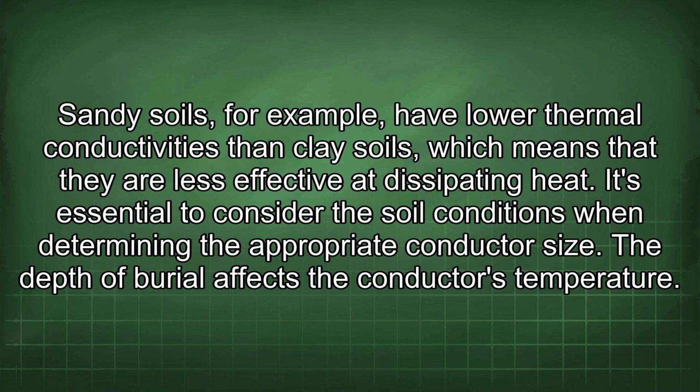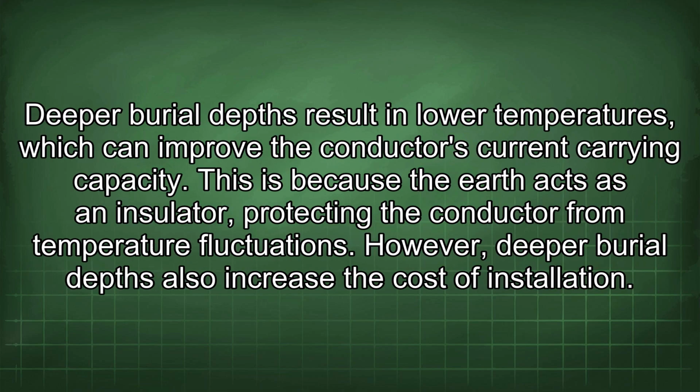The depth of burial affects the conductor's temperature. Deeper burial depths result in lower temperatures, which can improve the conductor's current carrying capacity. This is because the earth acts as an insulator, protecting the conductor from temperature fluctuations. However, deeper burial depths also increase the cost of installation.